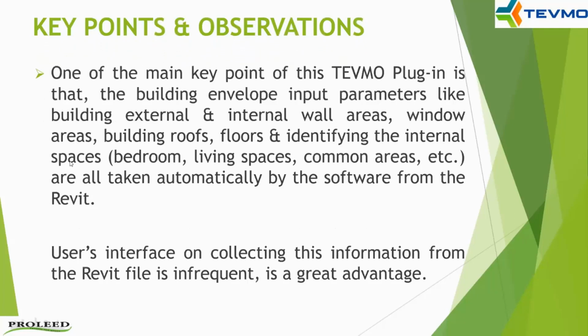So one of the main key points of this demo plugin is the building envelope input parameters like external and internal wall areas, all the fenestration window areas, building roofs, floors, identifying the internal spaces like bedroom, living spaces, common areas, all will be taken automatically from the Revit by the software. So that is a great advantage for the designers for the cooling load calculation, because basically the user's interference on collecting this information, the building envelope informations, is very less from the Revit file, which is a great advantage.